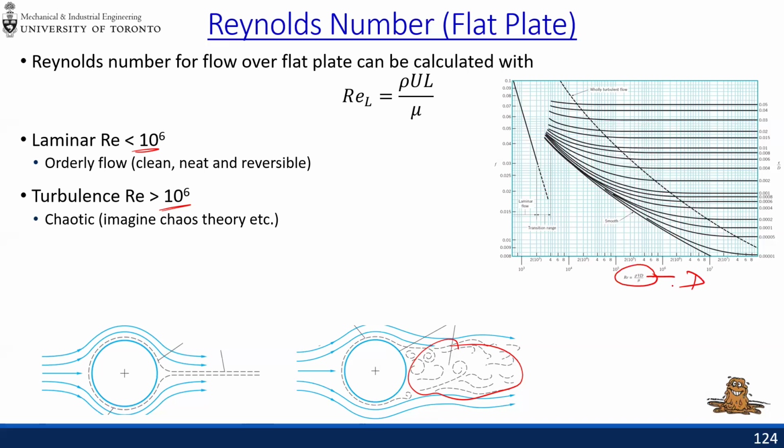Now, another thing with the Moody chart, so you have your laminar here, and then these are basically all your turbulent, this whole segment on the right. There's a little pocket called a transitional range. Now, the transitional range isn't laminar, and it's definitely not turbulent either. It's somewhere in between, and you can probably say, oh yeah, it just suddenly shot up.